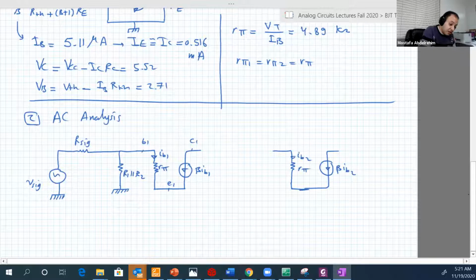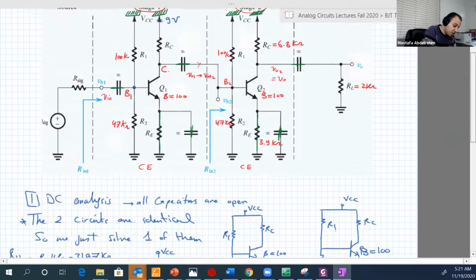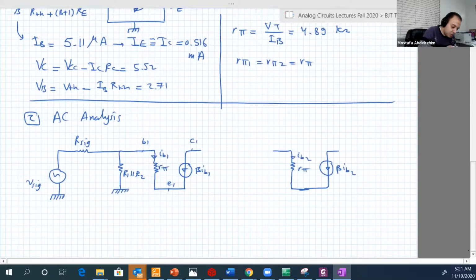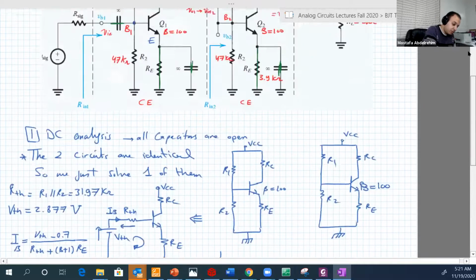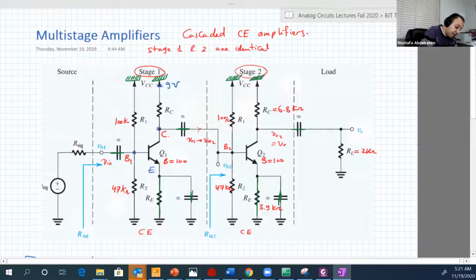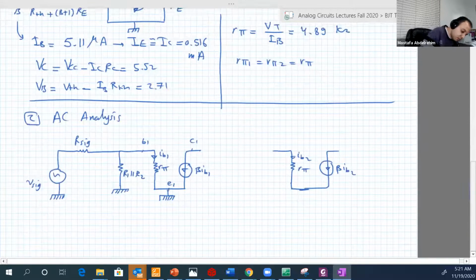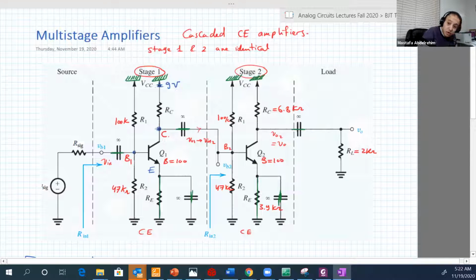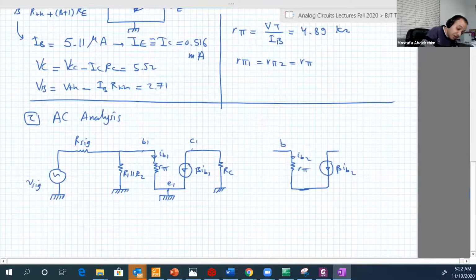Now let's connect emitter 1. So here is the emitter of the first transistor. And as you see, because we shorted RE, it's connected to ground directly. So it's connected to ground here. That's good. Now collector 1. So between collector 1 and the ground, remember VCC now is grounded, we have RC. And collector 1 is connected to base 2, I'm sorry.